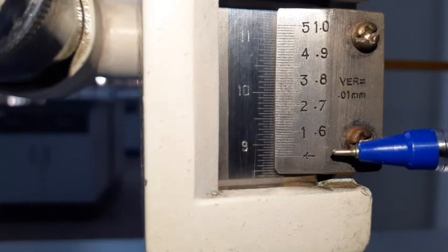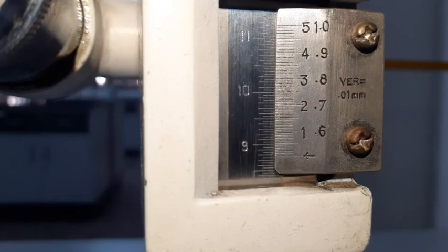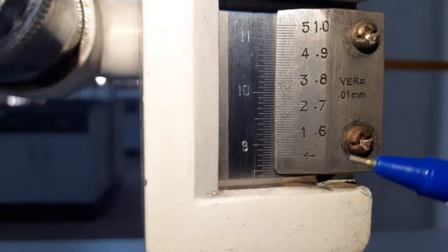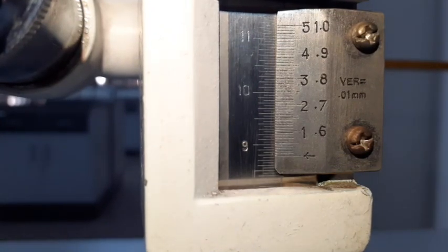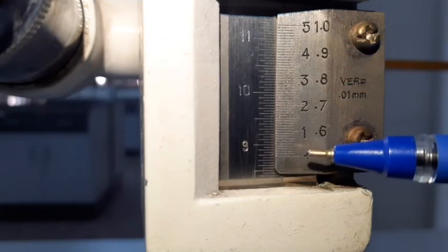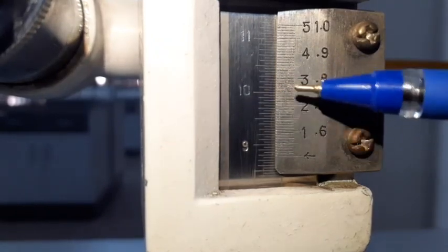Here, as you could see, the 0 of the vernier is exactly in between 8.75 and 8.8 of the main scale reading. Since it has crossed the minimum point of 8.75, the main scale reading for this particular portion is 8.75, and the vernier scale coincidence is noted by seeing the exact division that coincides with the main scale.